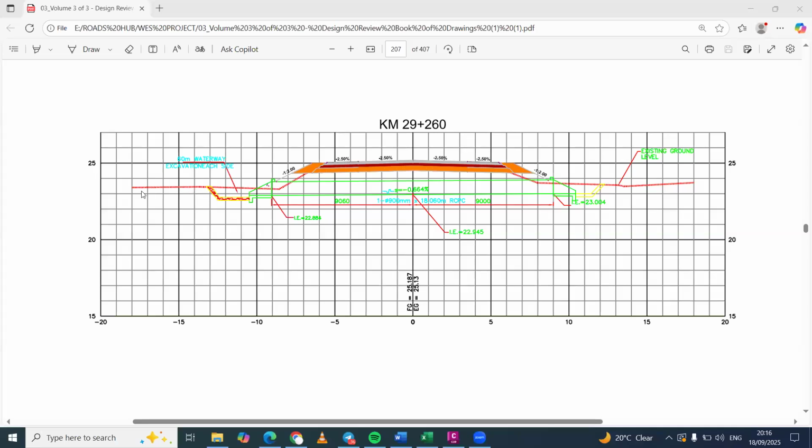We had not created it yet, but the software already had all the information. The moment you did your sample lines, it was able to get cross sections from that, then calculate the volumes using the average end area method, by estimating cut areas or fill areas, then multiplying by the difference in intervals at which it's getting those areas, basically the intervals of your sample lines.